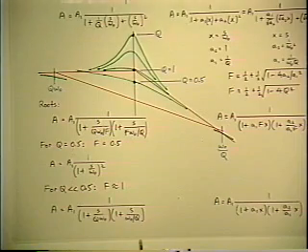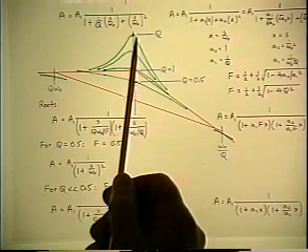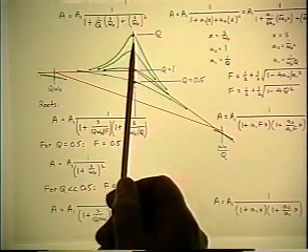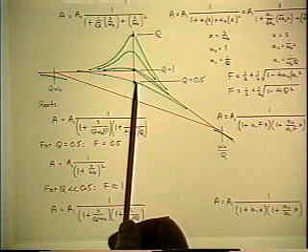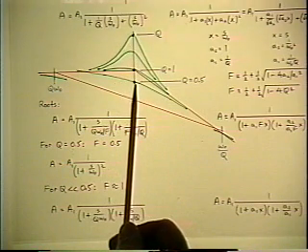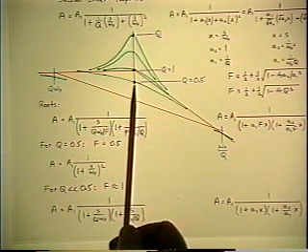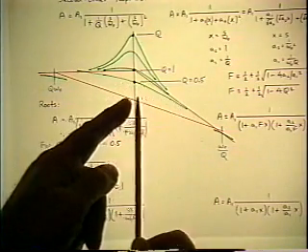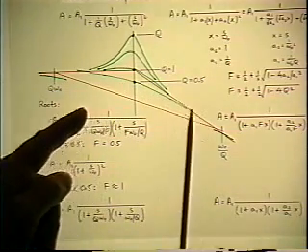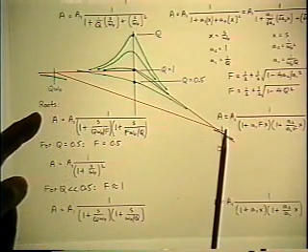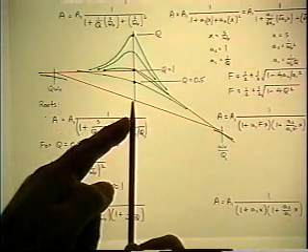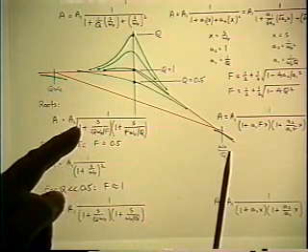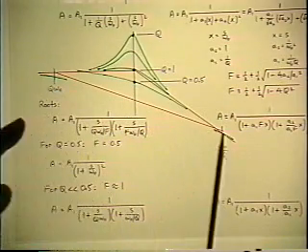So visualize now the spectrum of values. If Q is high, you get complex roots, you get a peak. If Q comes down, the peak comes down. You go through a transition at Q of 0.5, two equal real roots, and if Q drops below 0.5, those two real roots simply spread equidistant on both sides of the original corner. Equidistant because it's a log scale, and one of them is Q times the corner, the other is 1 over Q, so that's why they spread equally on both sides.